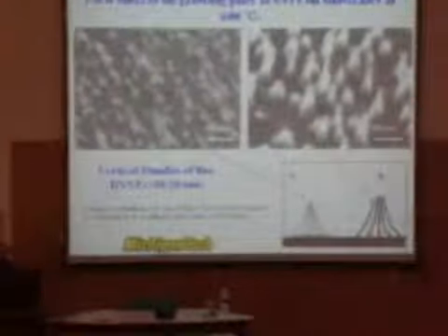So we just have to put some nano catalyst, and the plume that strikes the surface will bounce away, except those that stick on the catalyst. If they stick on the catalyst, they will dissolve in the catalyst and be captured inside, and then they will segregate out to form the boron nitride tubes. And you can see the clean bundle of the tubes, like this, vertically aligned on the substrate. This one is bigger diameter. You can see individual boron nitride tubes vertically aligned on the substrate.